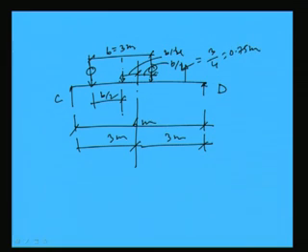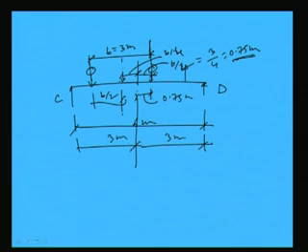That means one wheel has to be placed at a distance of 0.75 meter from CG of the span. So if we keep this, then only we will get the maximum bending moment, and W we have calculated, the two wheel loads are calculated. This is 191.96 kilonewton and this is 191.96 kilonewton, right.